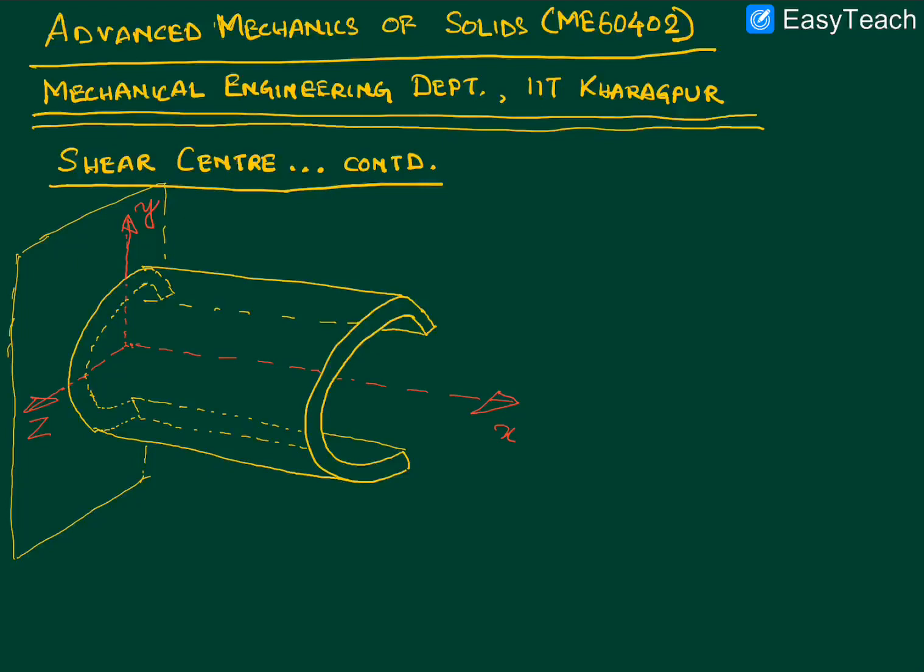And please remember that there we had actually considered the y-axis and the z-axis to be centroidal axes. And if the y-axis and the z-axis are centroidal axes when we are using the formula for the bending stresses, so it necessarily follows that if we have to again use the formula for the bending stress or anything that has to do with the mathematical derivation of the unsymmetrical bending, then it is also necessary that the x-axis has to pass through the centroid. So you have to remember that. But for most of the discussion, we don't require the x-axis to be the centroidal axis. Okay.